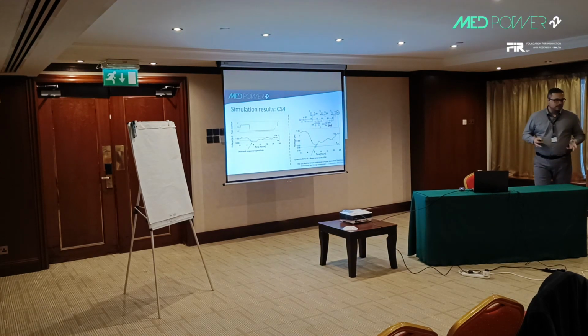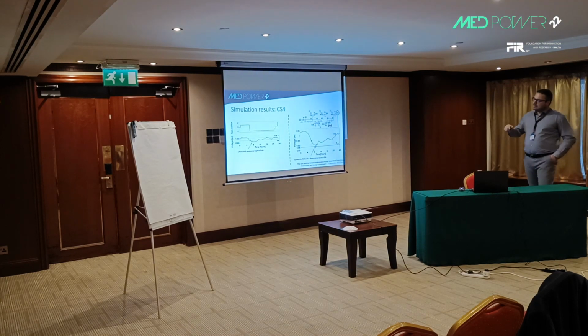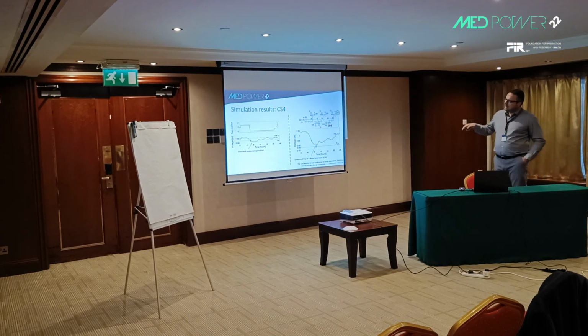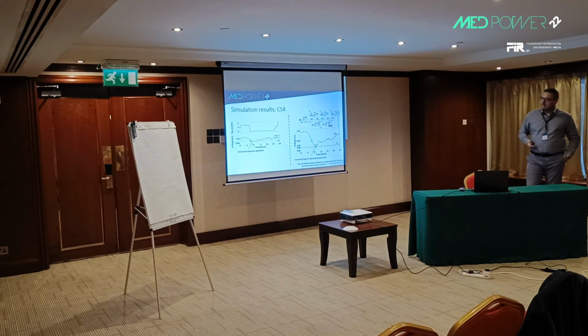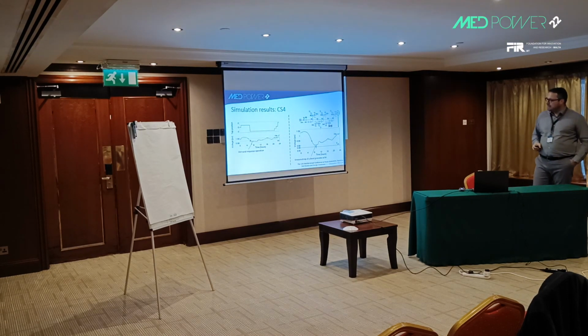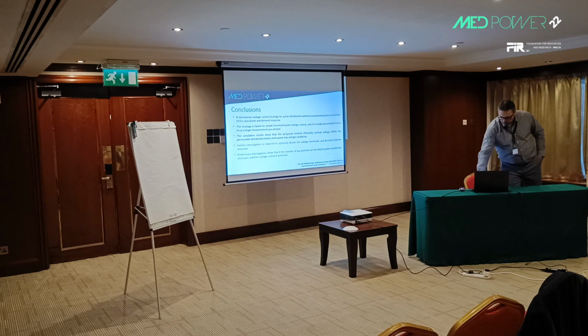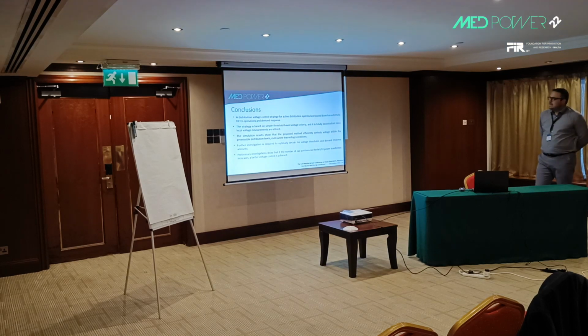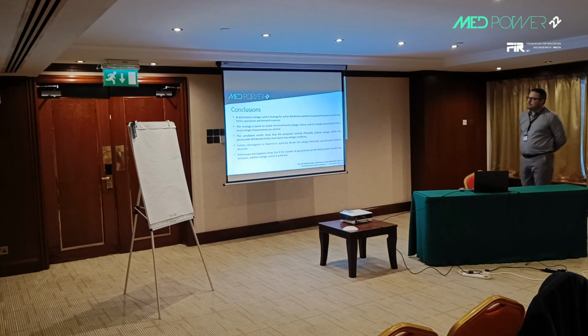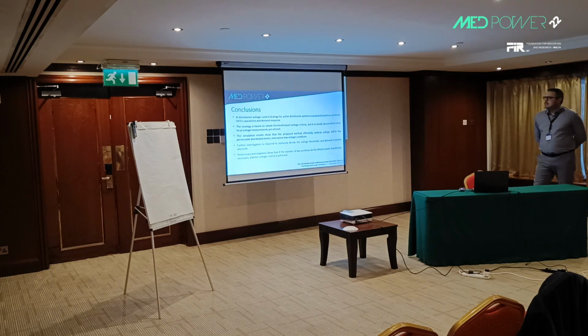You have two successive DG unit trips, however, the combined operation of the transformers with demand response actions also succeeds in keeping the voltage within the permissible limits. So, a distribution voltage control strategy is proposed based solely on automatic voltage operation and demand response. It is a fully decentralized scheme.